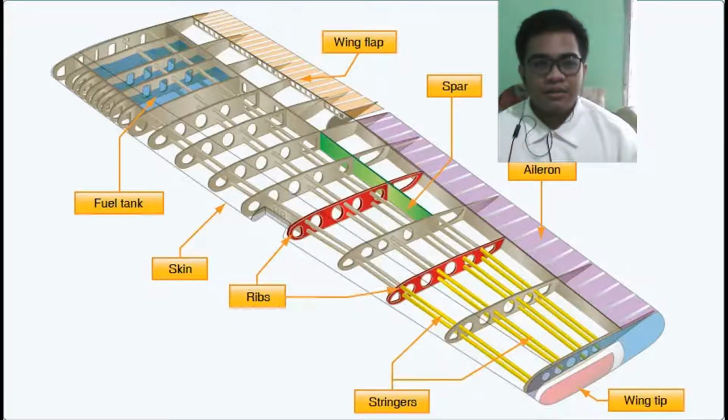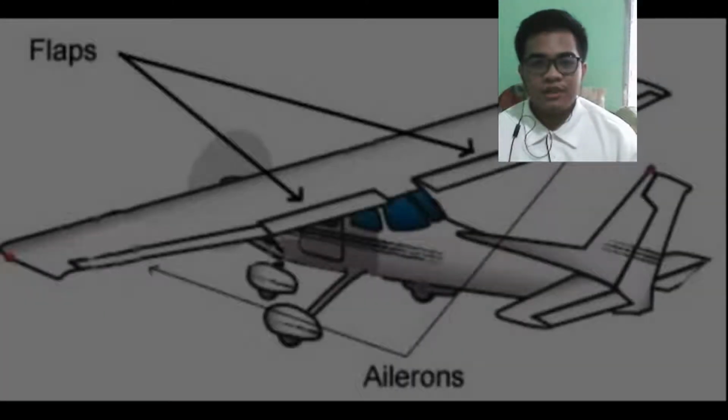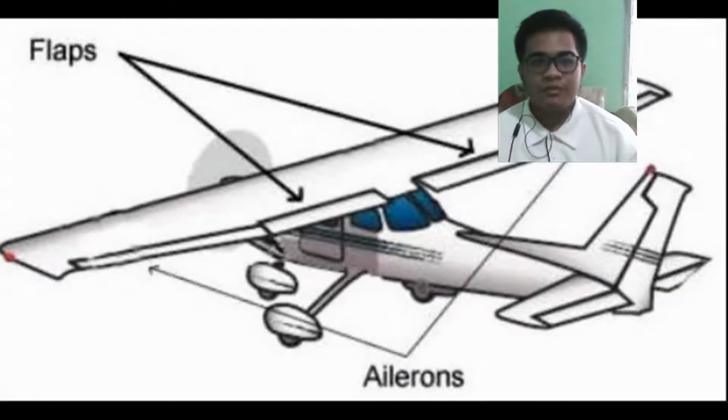The wing has two control surfaces, namely the ailerons, which are located on the rear outermost regions of the wing and move in opposite directions, which forces the aircraft to roll, and the flaps, which are located at the rear innermost regions of the wing and extend downwards simultaneously to create a bigger angle of attack on the wing, which can create lift and drag, thus preventing a potential stall.